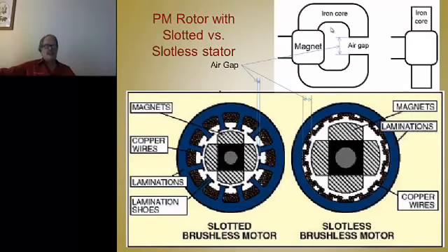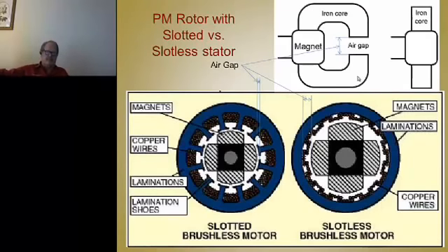So we're cutting this thing apart here with a hacksaw, and we're going to stick a magnet in there. So you've got a north pole there and a south pole there. So we've got flux flowing around here like this, and it jumps across this air gap, and we're defining the air gap. So now let's conceptually turn the components of that circuit into a couple of electric machines.